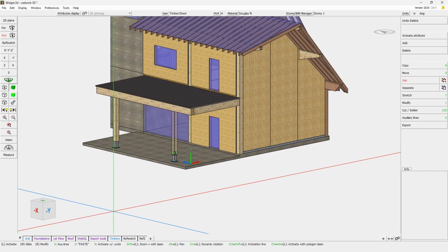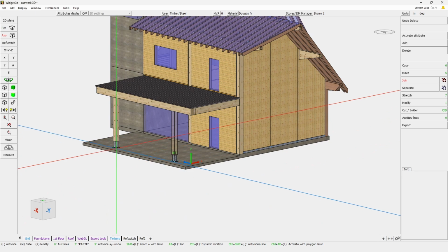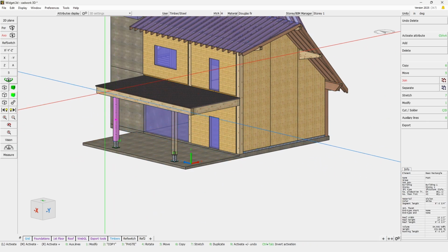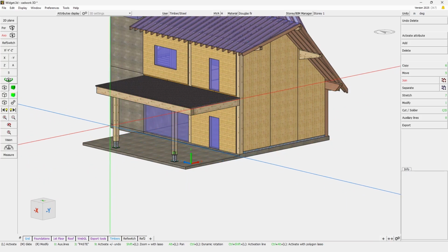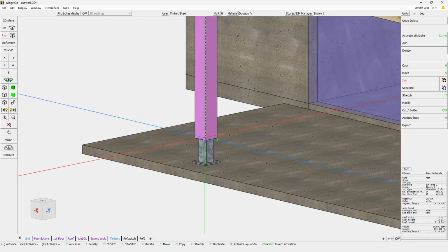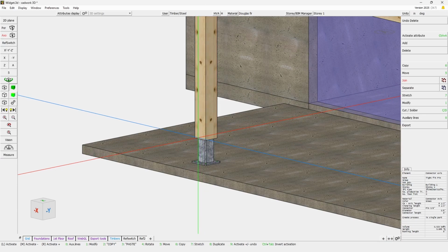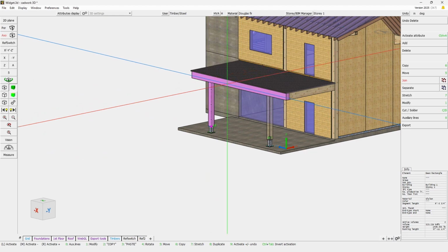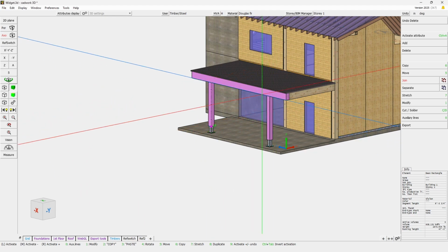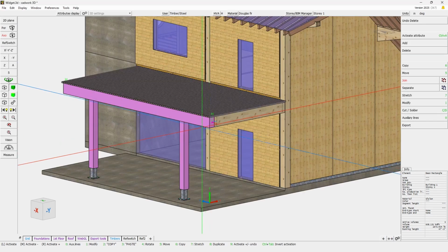One trick here to keep in mind is how you can easily change the location of an active point. The active point, for those of you who don't know, is added when you left click on an element. So basically when you start a selection. If I were to continue my selection by adding right click, I could then move my active point to any other element using control right click. So you can place an active point, set an active face, or an active edge. It simply depends on where you click.